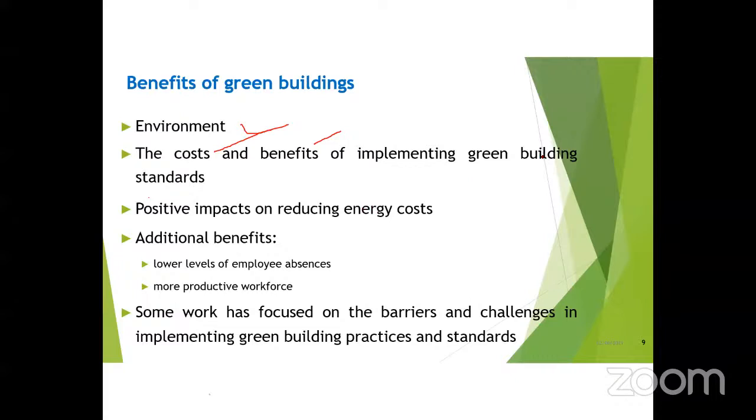Welcome, ma'am. So we are talking about the renewable energy utilization. Our green building utilizes the renewable energy. Green building consumes 40 to 80% less water as compared to the conventional building, as we are using the aerators in the tap. Whenever you go to the mall, you can take a mug and measure the time to fill that mug, and you can go to the ordinary tap and measure the time to fill the mug by the tap that we have installed the aerators in.